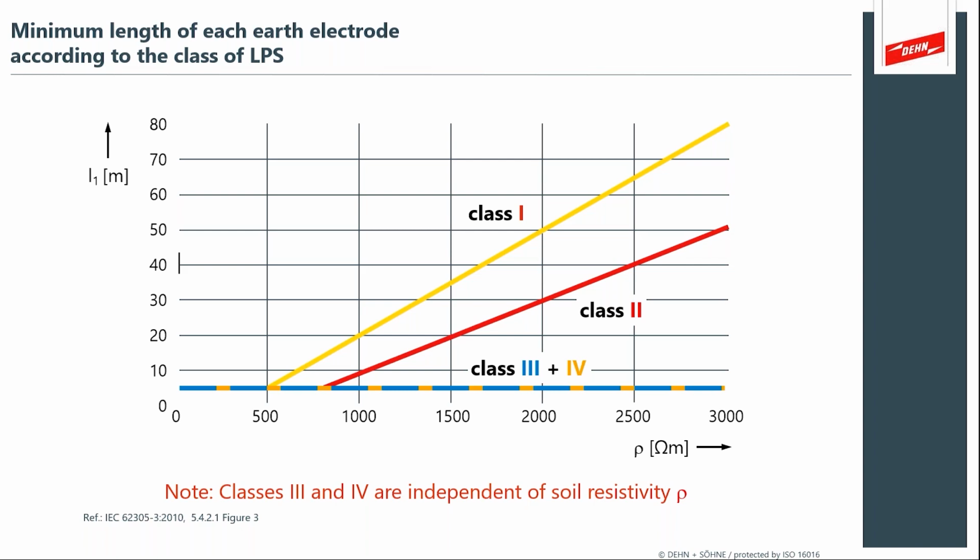What also happens is that you see customers have their own relative requirements for electrode placement and electrode impedance with the soil. So for instance, we have power utility companies that want a 1 ohm electrode contact with the soil.